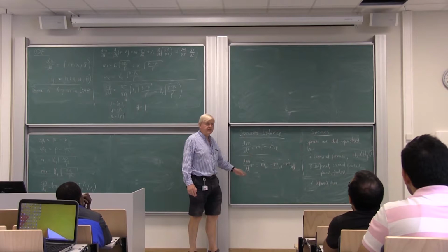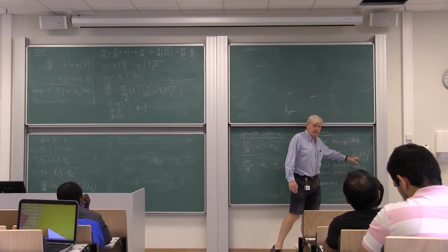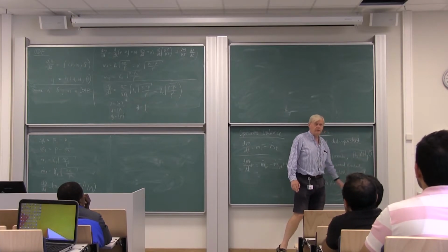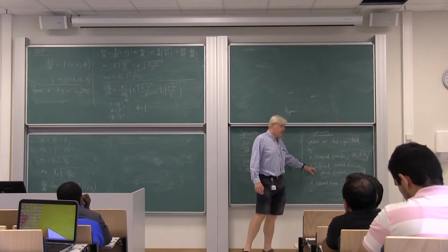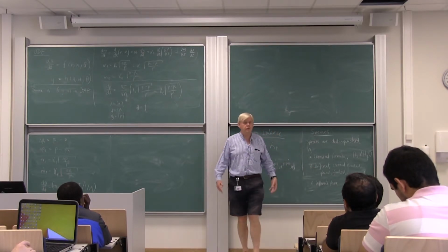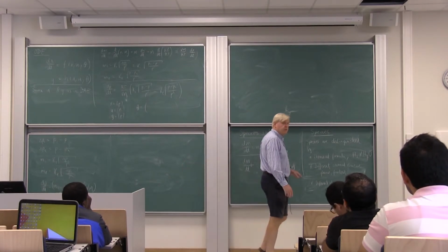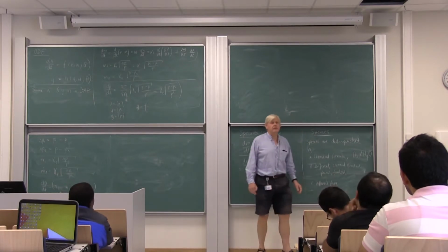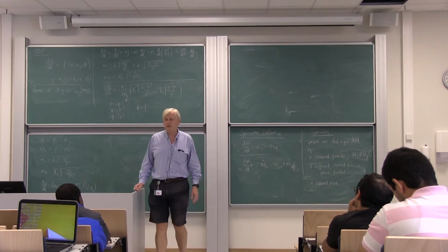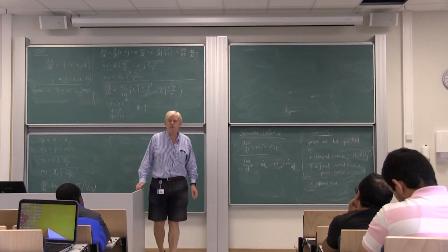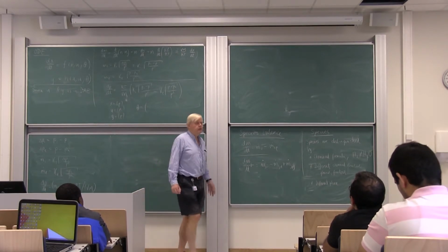We have to formulate a different species balance for each. If species have different chemical formula, we need different species balance for them. If they have different chemical structure, like glucose or fructose and so on, they are different species, and we need a separate species balance. And if they have different phase, like water in liquid phase and water in gas phase, then we also need separate species balances. Okay? So that's the idea.